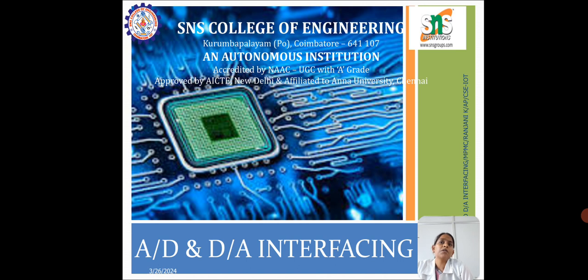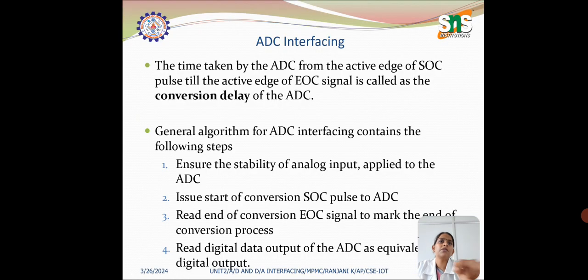Another important specification for an ADC is its conversion time, which is the time the converter takes to produce a valid output binary code for an applied input voltage. When we refer to a converter as high speed, it has a short conversion time.